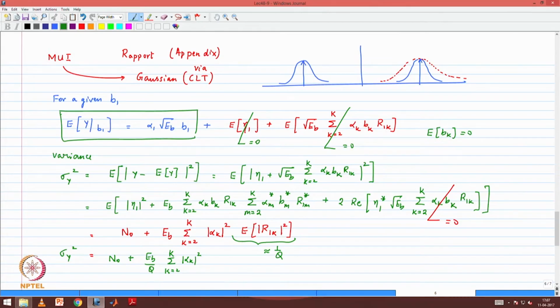Now we get into the very interesting parts of this discussion. This is a CDMA system where we do fast power control, and so we will pick up several of the key concepts that we have discussed earlier. So this is the uplink. The mobiles are transmitting to the base station, and the base station is the one that controls the transmit power.